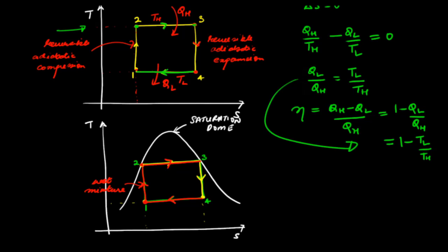Similarly, if we have this heat rejection from 4 to 1 occurs over a small or infinitesimally small temperature difference, then the heat engine would operate reversibly. Thus, except the compression process, all other processes are realizable, though in reality they will also be irreversible.